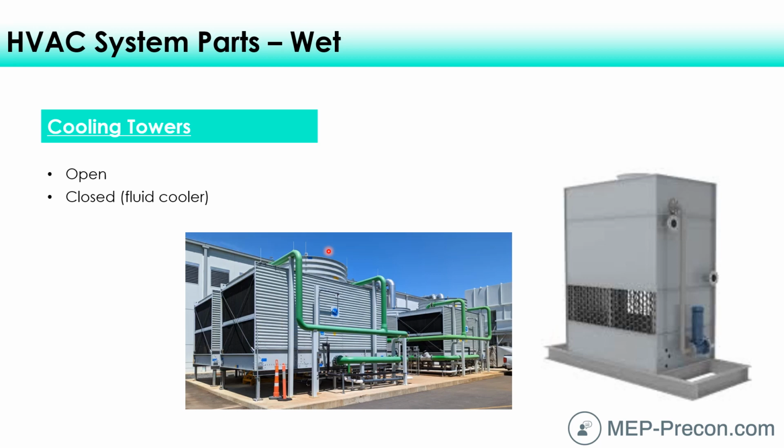To get rid of that heat, we get rid of it through a cooling tower, and it could condense in the wintertime, and that fog plume could blow up against guests' windows and maybe even fog up the exterior of those windows, even if it's not raining. And it could create kind of an undesirable experience for the guests. So just something to think about.